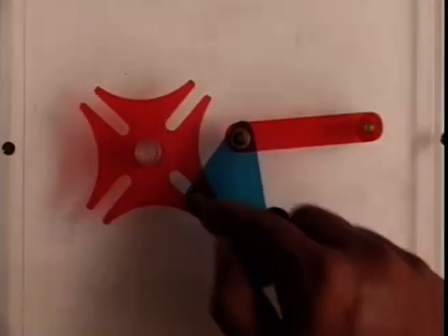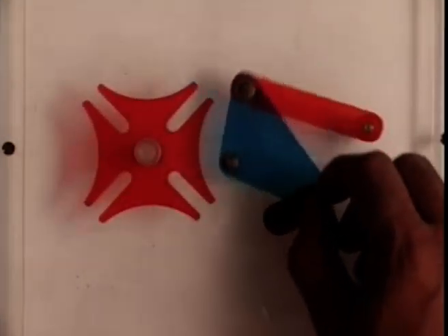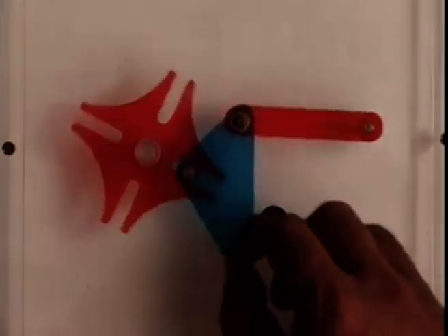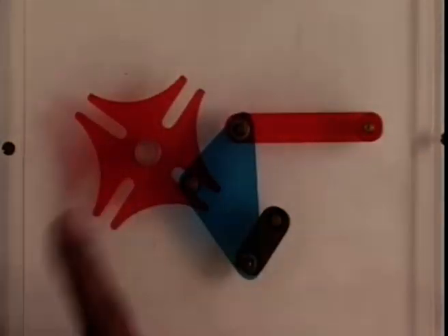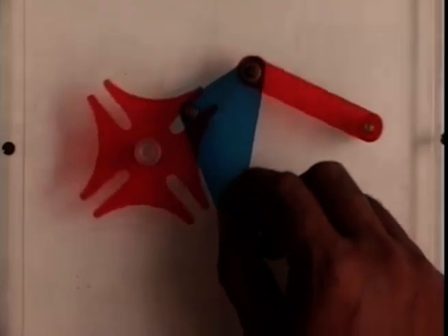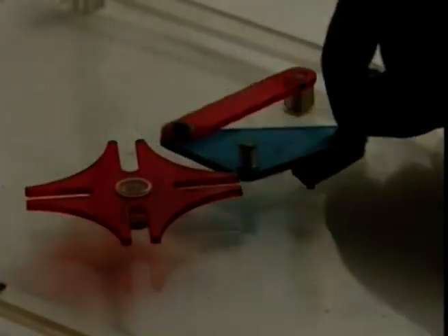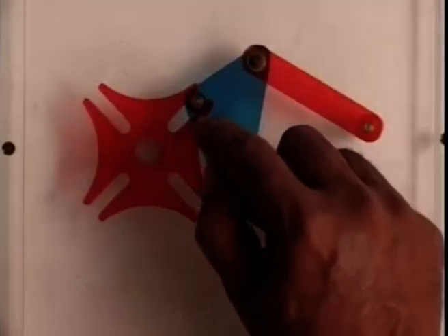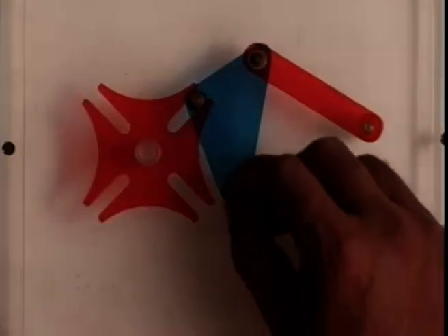And if we have a coupler curve such that the tangents to the coupler curve are along these two directions, then the entry and exit from this slot is very smooth. Consequently, we can use this particular coupler point to drive the Geneva wheel. So this is again an example of a path generation problem, because we have to generate this particular path by this point such that the tangents to the path are along these two slots at 90 degrees.